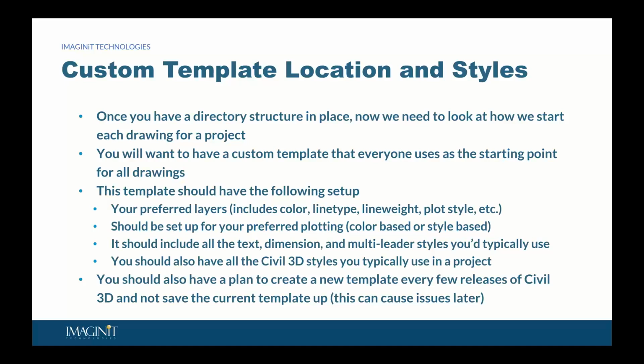When creating a new template for a new release, is it okay to import the styles from the old template? Yes, absolutely, it is how I typically do it. If a style cannot be imported into a new template from an old one, it will tell you that that style did not import. It'll give you an opportunity to investigate that style and either rebuild it or figure out what's wrong with it. So those are the things that we need to be careful of with custom templates.